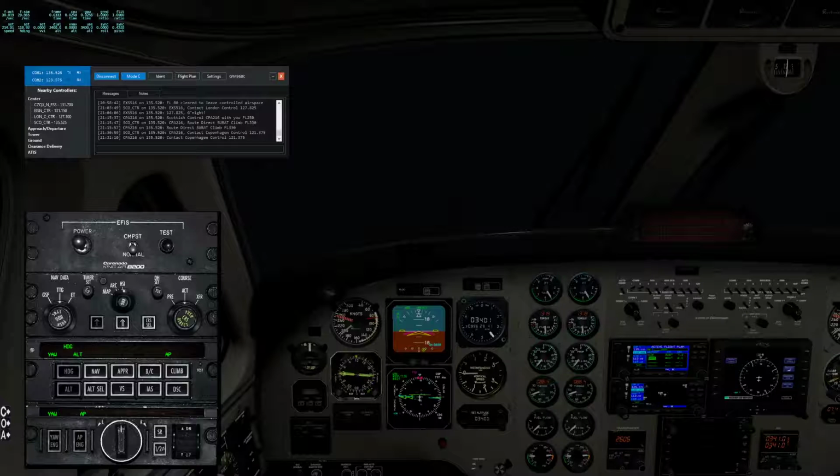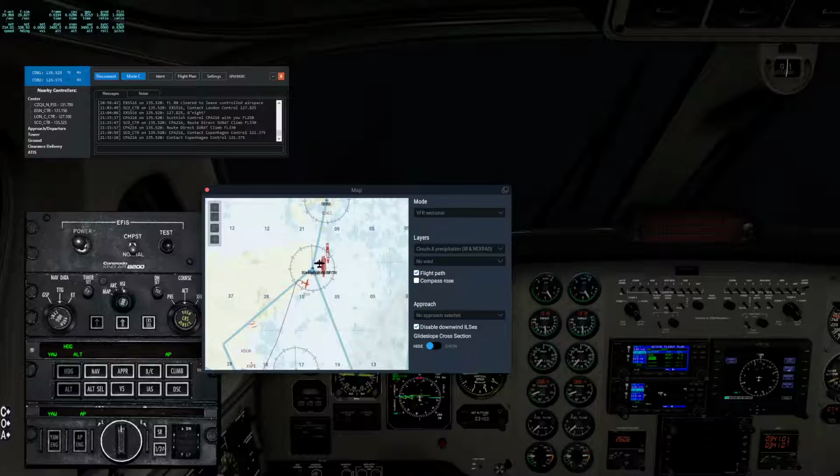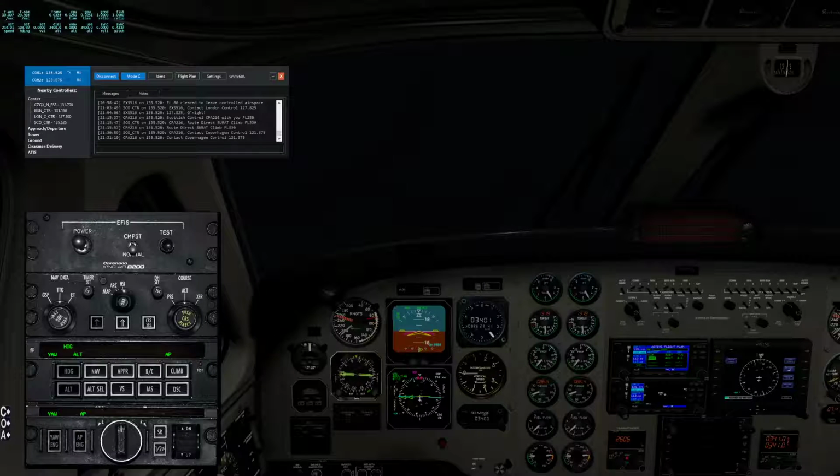Distance is about 7.4, so that's not too bad. We need to be about 7 miles out, so that's sort of within limits, I think. Now I'm going to do turn 10, twist 10. So each 10 degrees we steer left 10 degrees and change the bearing 10 degrees. And essentially we just keep doing that, keeping an eye on the distance, trying to keep it round about 7, and then we should be following the arc.